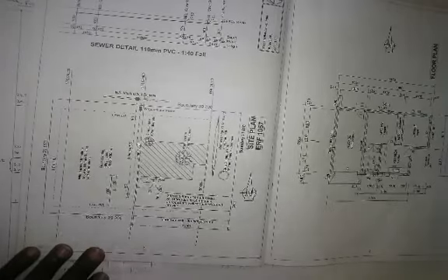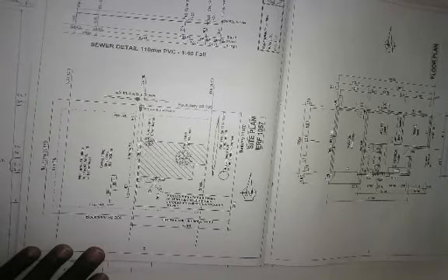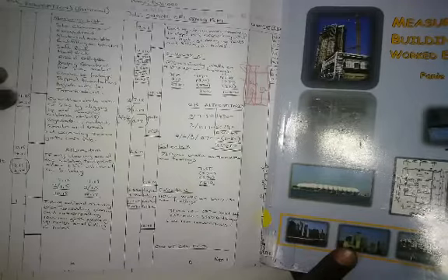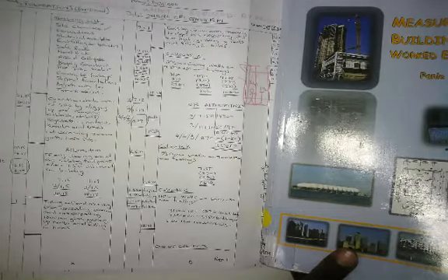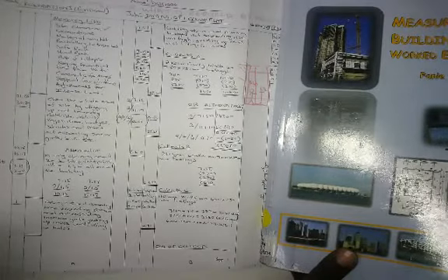So your dimensions for the entire site, your first dimension is 21,850. There it is. Second dimension, 30,200. That's your second dimension. Remember, site clearance as per standard system, we measure it in square meters. Okay. So you say length times breadth, then that's sorted. Then you take your dimensions and input it in your times column over there. 21.85 times 30.20. That's your site clearance. Alternatively, guys, they can say to you, please don't clear the entire site.